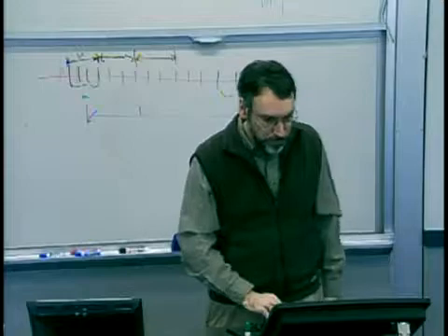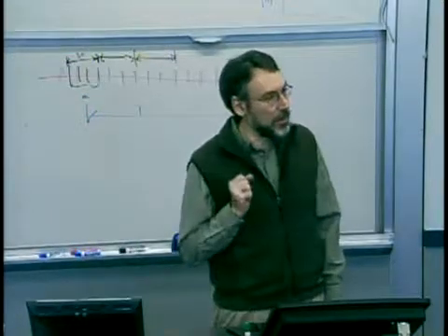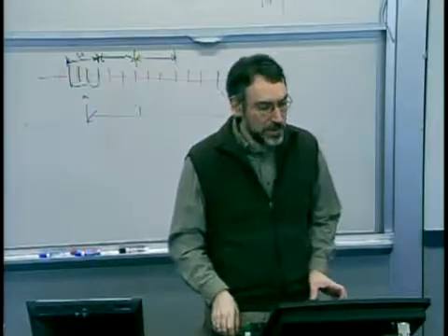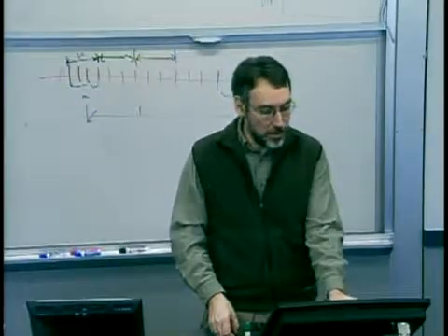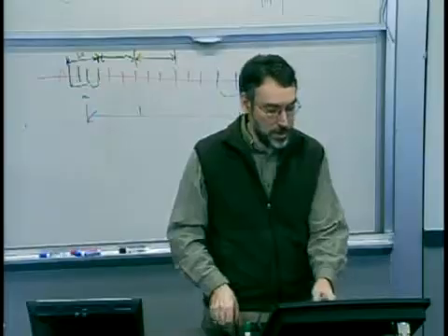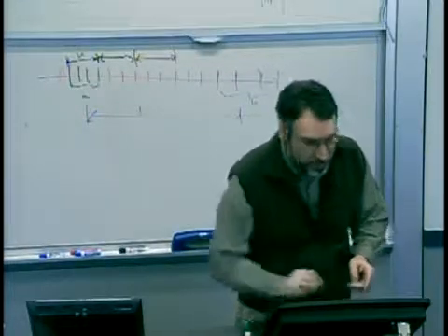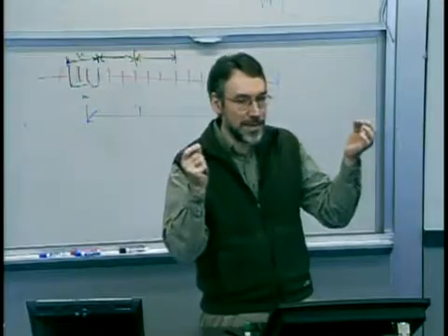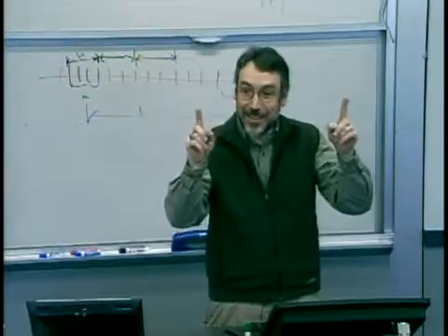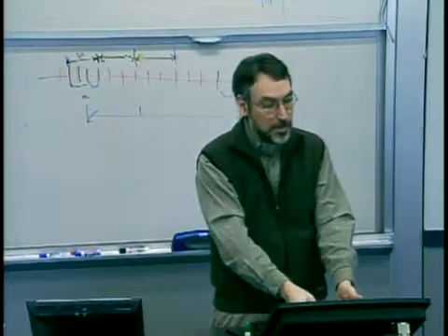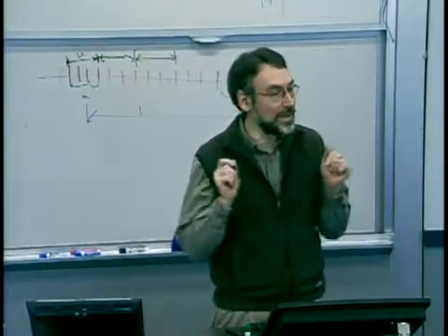Okay? Now let's consider a slightly different picture. Here I have my spec limits different from my, or basically my x bar or x star here and my mu are very different. My process spread is exactly the same as before, right? I still have an upper spec limit minus lower spec limit equal to 6 sigma.